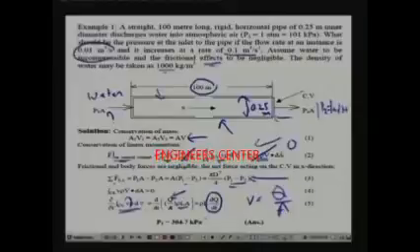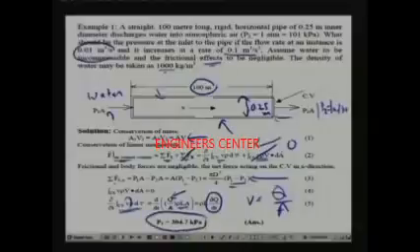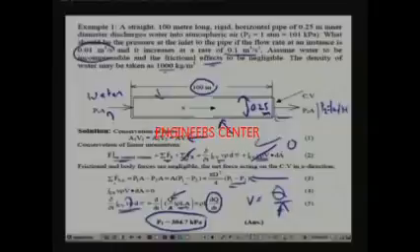these values here and then use the equations 1 to 4, you get the answer P1 is equal to 304.7 kilopascal absolute. That means the pressure here should be 304.7 kilopascal, so that the flow can take place. This is a very simple application of linear momentum to a pipe flow, and the same linear momentum principle is used in many other applications, and when we discuss the fluid flow aspects through refrigerant pipes and ducts, we will discuss these issues.